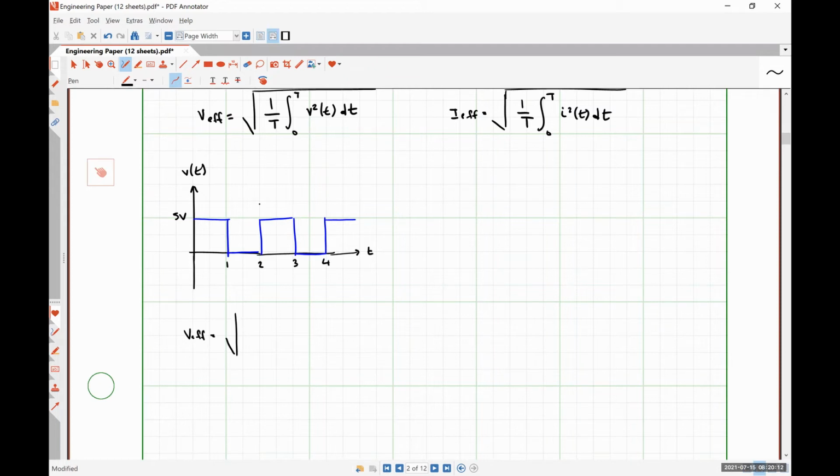So it takes exactly 2 seconds to complete 1 cycle. It does not matter if we start measuring from the leading edge of our rectangular pulse, or the trailing edge, or the midpoint of our pulse. As long as we're integrating over exactly 1 period, we're going to get the right answer.